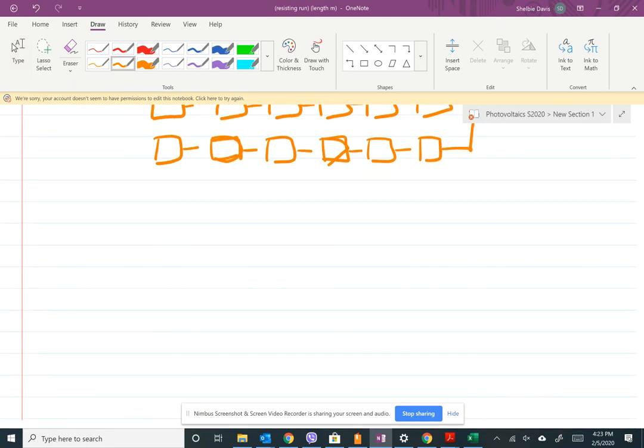High temperature V. We're going to use the VMPP because remember, VMPP at NOCT is going to be on the lower side of your voltage. So VMPP at STC is higher than VMPP at NOCT, so you're just going to use the NOCT one for the lower range. So this is what we just found. That's from the spec.